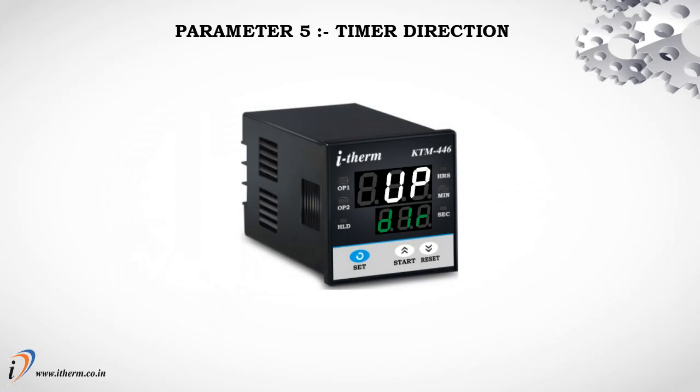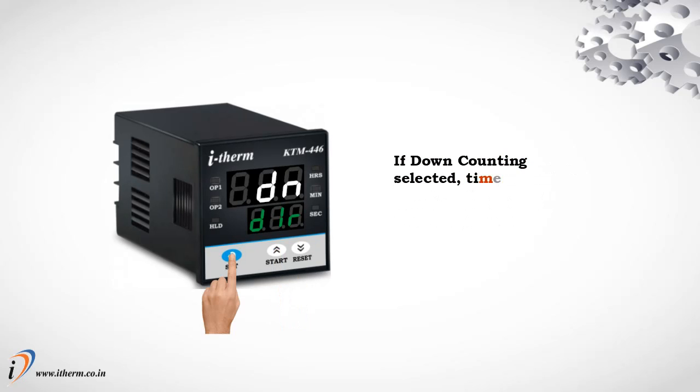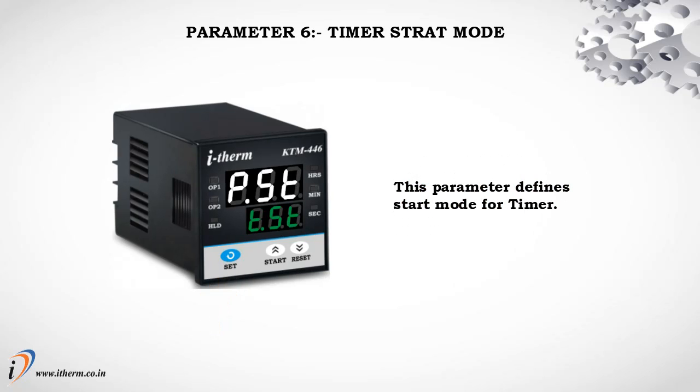Parameter 5. Timer direction. If up counting is selected, the timer starts counting from 0 to the set time in ascending order. If down counting is selected, the timer starts counting from the set time to 0 in descending order. Parameter 6, timer start mode. This parameter defines the start mode for the timer.